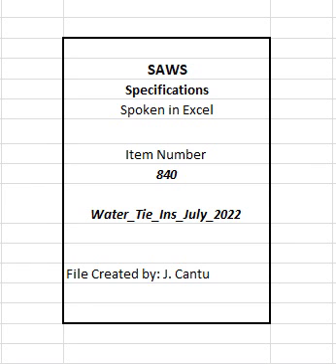connected, cutting pipe for the connection, dewatering the excavation, assembly, excavation, selected embedment material, initial backfill, secondary backfill, anti-corrosion embedment when specified, compaction testing, blocking, transition coupling, all required restraints, accessories, and appurtenances, hauling and disposition of surplus excavated material, including all existing pipe, fittings, appurtenances to be abandoned or removed, surface and pavement restoration, installation of all weather surface, dewatering of the main, other required testing, temporary service connections, customer coordination, and customer notification of service interruption where required.